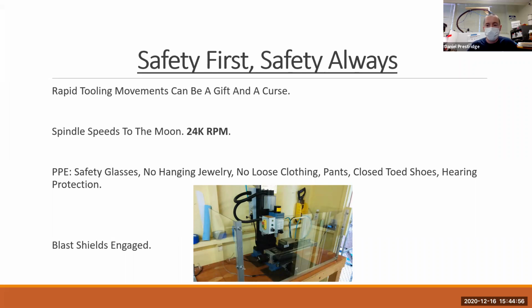So that's number one. And then, of course, hearing protection. Aluminum is very loud. The air system that they use, and you would probably use maybe for cooling down the chips or blowing away the chips so that you don't continue eating through them, is loud. And then also the vacuum, if you're using some kind of suction on there, that's also very loud. So the combination of all of those things can damage your hearing over time. It might not even take that long.